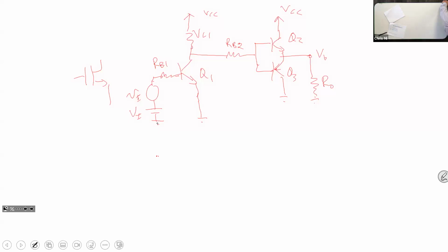In this case, it's particularly true because that little vi is so small. The capital VI is 0.7, and little vi is 5 millivolts. So 5 millivolts over 0.7 volts is less than 1%, right? So even if we neglect that lowercase vi, you won't be too wrong for the circuit analysis when you do DC. Okay, so lowercase vi is 5 millivolts.